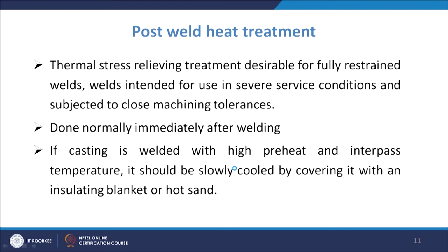This is done normally immediately after the welding, and if the casting is welded with high preheat and interpass temperature, it should be slowly cooled by covering it with an insulating blanket or hot sand, as we have discussed. If you insulate it, the thermal gradient developed will be smaller, and the chances of defects will be smaller.